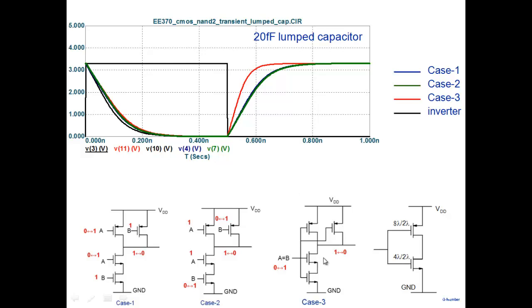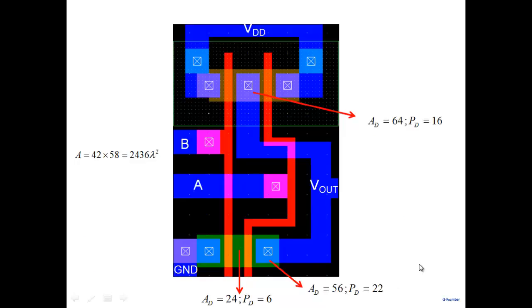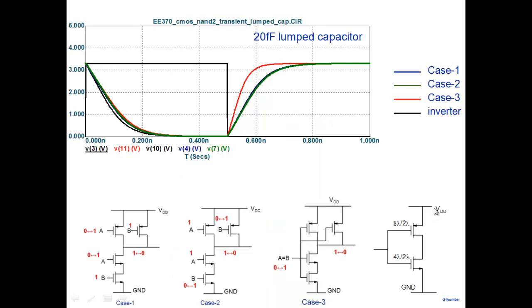Anyway, all this example illustrates is that we size them properly. We size them such that the pull down strength is 1x like this one. This example is only showing that. Now, to actually estimate delay, we have to put in capacitance properly. I can't just take a 20 femtofarad capacitor arbitrarily and put it here. What capacitor to put, we have to get it by looking at all the drain, body, all those capacitances here.